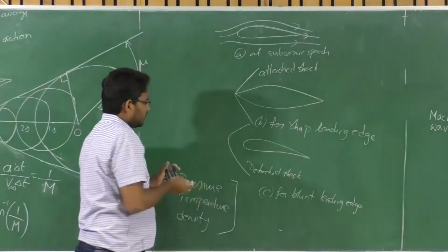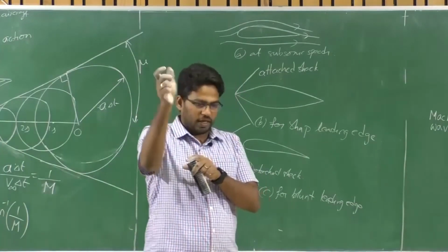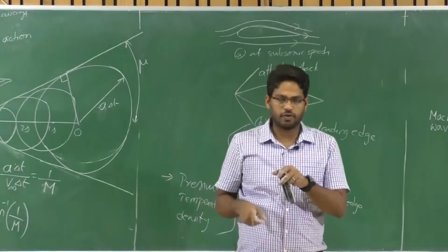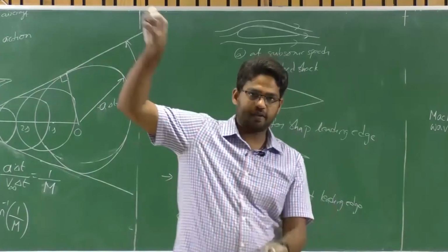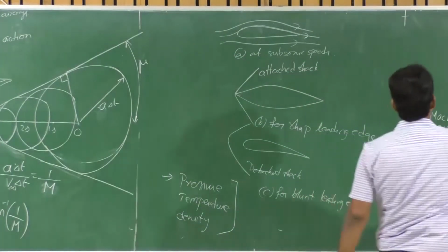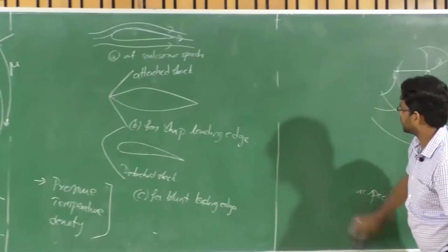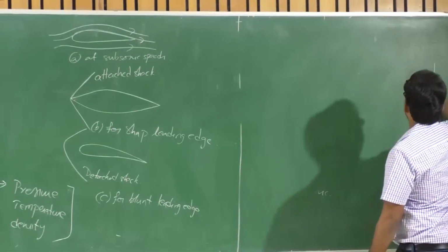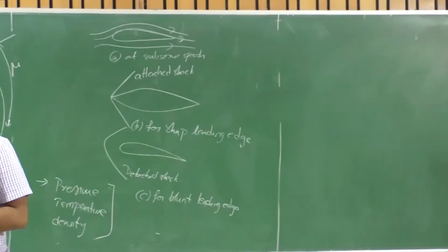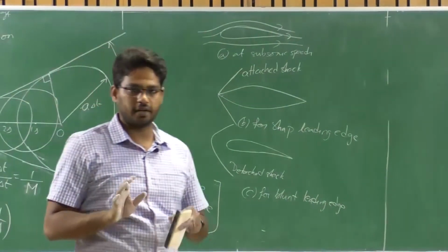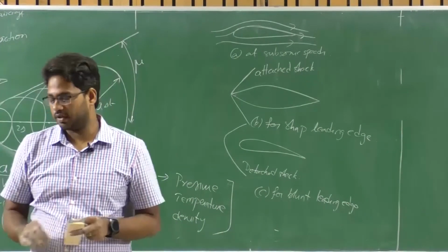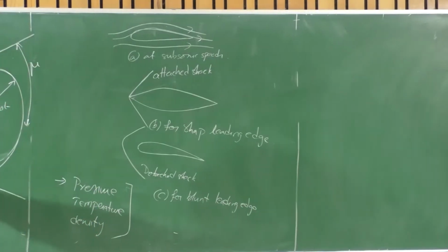So this pressure is nothing but the compression of the mass of fluid particles which are ahead of this flying object, right? So these compressed fluid particles will offer additional resistance to its motion. That additional resistance to the motion, apart from the skin friction as well as pressure drag, is the wave drag. So the wave drag is due to that additional resistance by the fluid particles across the shock, for the aircraft to move in that particular fluid. Okay, so that's the story about this wave drag.